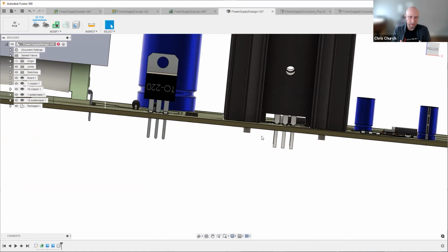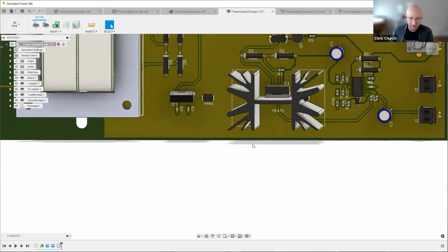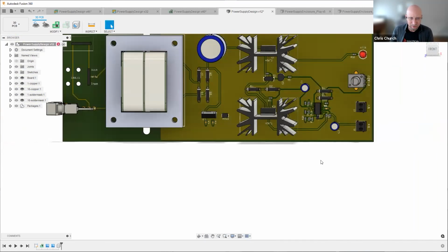So you're going to need some sort of heat transfer paste, the same as you would see on the CPU in your computer between the fan and the CPU. We're going to need some kind of heat transfer paste because we can't rely on just that physical connection. And this is something that's not going to show up in your E-BOM in a lot of cases, right? This is a consumable, but we need to talk through what the process is. We can use heat tape, etc. But if you could give me the top view, I want to see something here as well, because I see something that's concerning me and that our engineers would be concerned with as well.